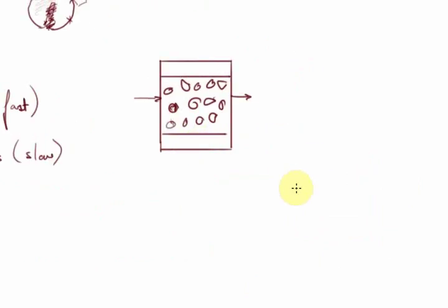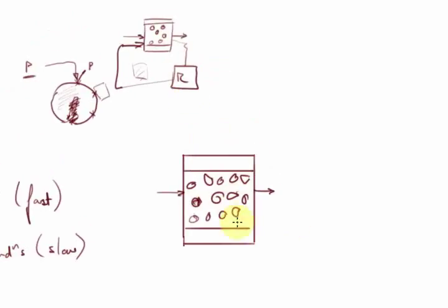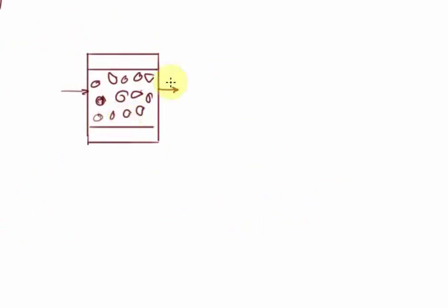Now, if it's going to take 2 years to deactivate this catalyst, we don't want to go and introduce regeneration loops and so on. We would rather look at operating such that we achieve a higher reaction rate here. And of course, when we lose activity, let's represent activity as a little a, and that's in time. So when we say we are losing activity over a period of 2 years, we do not mean that we'll be operating at perfect activity until 2 years, and then we lose all that activity.